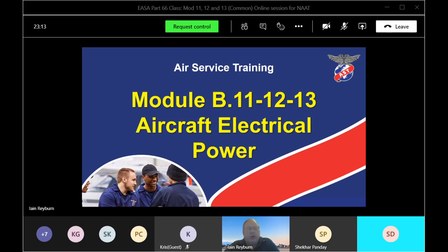So I could say I have the average, or datum, excitation voltage. But if I have a constant DC, what would happen is my output voltage would start to go up. If I kept 28 volts on all the time, I'd get 115, 116, 117, 118, 119, 120, 130. It would keep rising until it got far too high. If I turned it off constantly, I would get nothing. So when I have my normal output of 115, this excitation field will pulse on and off.